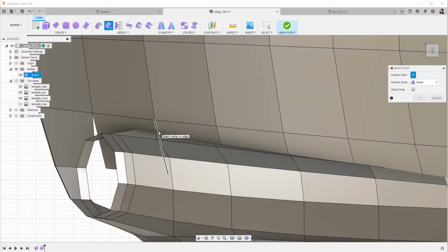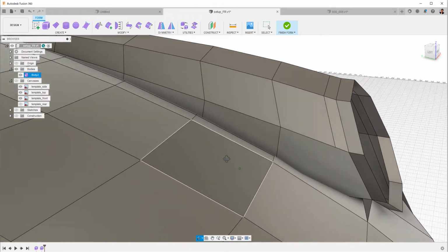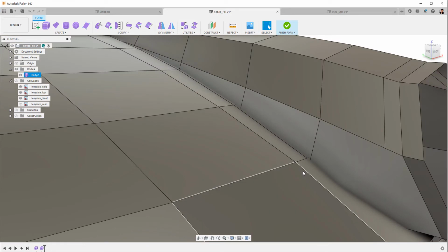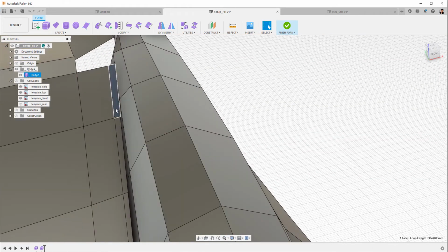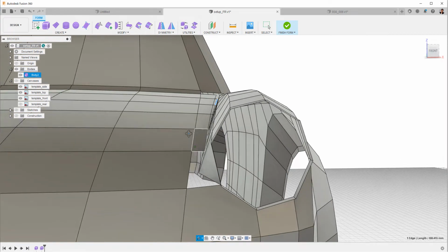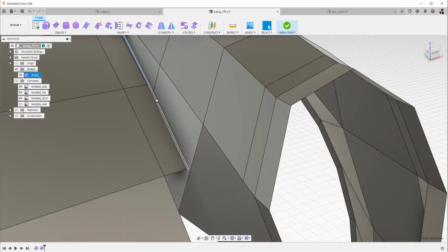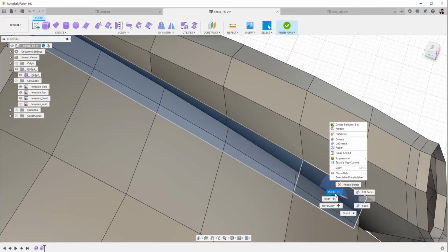Change to the top view. Then create an edge at the insertion point referring to the intersection. Delete this face once. Create an edge by slightly shifting the back edge like this at the insert point. And delete these parts. Remove this part of the fender and bridge the hood and fender anew.